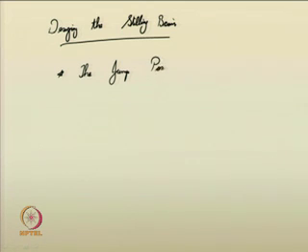We studied in the last lecture how the location of the jump can be determined, that is, how you can infer the location of the jump based on the depth of flow in the upstream as well as downstream conditions. So, the jump position is quite essential for designing the stilling basin.